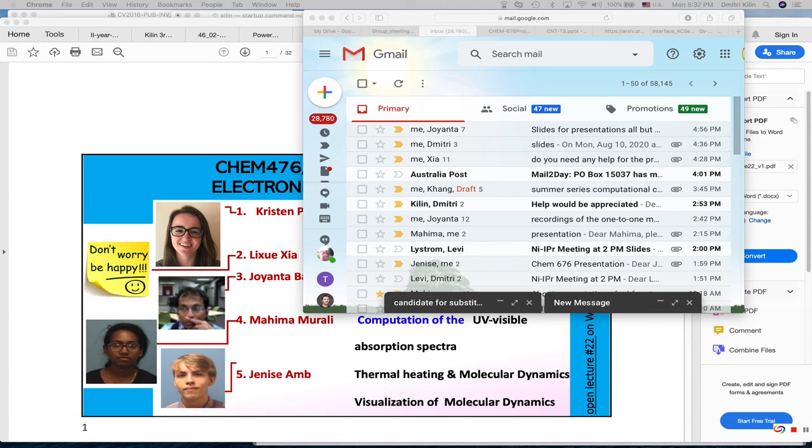And the third script is KPOINTS, and the KPOINTS file determines the sampling of the first Brillouin zone, which also contains 5 parts. The header is about the command of the file, and the second one, 0, means the automatically produced file generation scheme, and the third one is about the grid type.